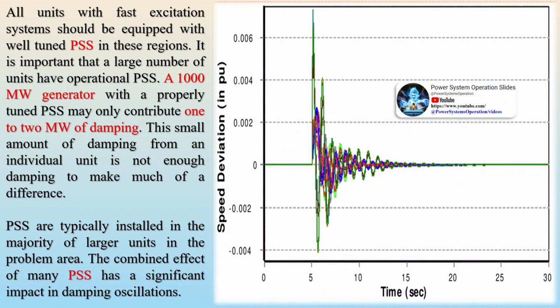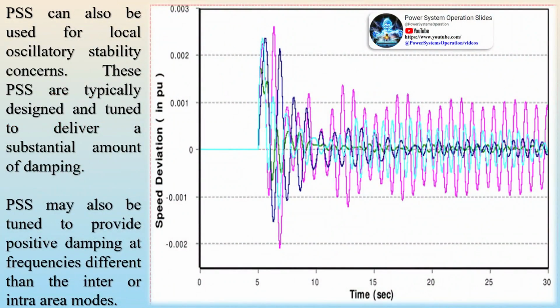The power system may require assistance with damping some low-frequency oscillations. PSS are tuned to correct an excitation system's response to low-frequency oscillations. A PSS is typically set to detect oscillations in the inter-area or intra-area modes, approximately 0.05 to 1.0 Hz. If these frequency modes are present, the PSS will send corrective voltage signals to the automatic voltage regulator. If the oscillations are outside of the PSS's tuned range, the PSS will not send any corrective signals. Without a PSS, fast excitation systems may cause system oscillations to sustain themselves or to grow in magnitude.